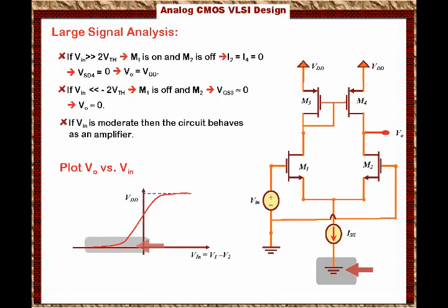So basically the bottom clip will be at the lowest voltage in the circuit, which in this case is 0 volts. It can be minus VSS. It doesn't have to be 0 volts. So keep that with you, and we will use this concept when we move to the operational amplifier lecture in a few lectures down the road.